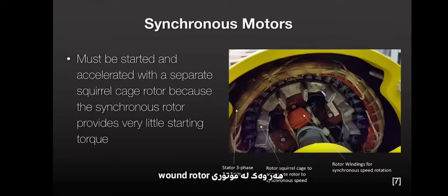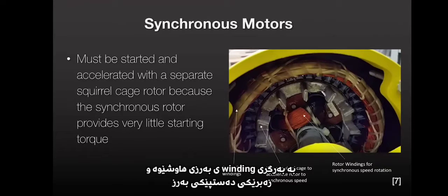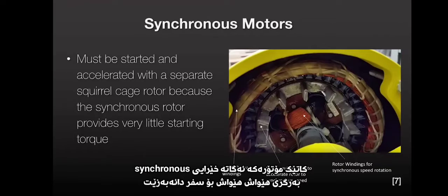When the stator is excited, the synchronous motor starts like a wound rotor motor with similar high rotor winding resistance and high starting torque. When the motor nears synchronous speed, the resistance of the external rheostat is gradually reduced to 0.